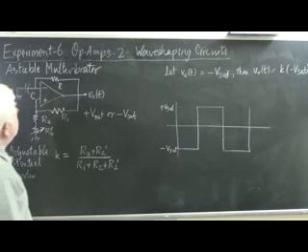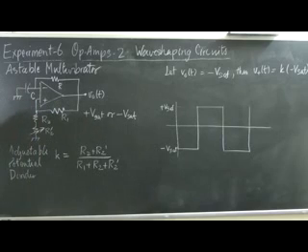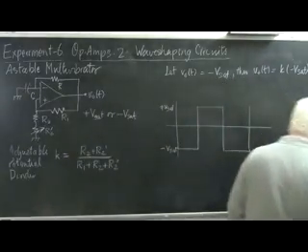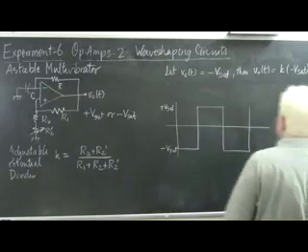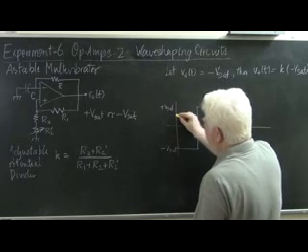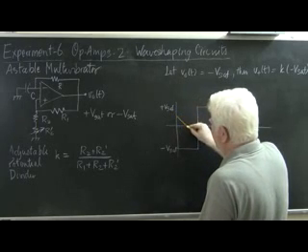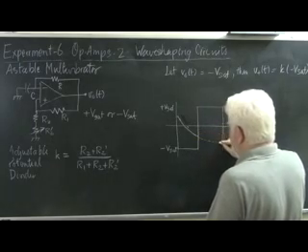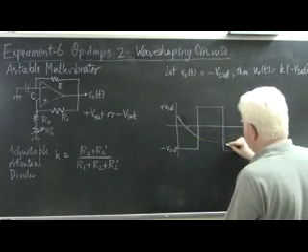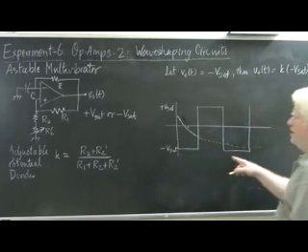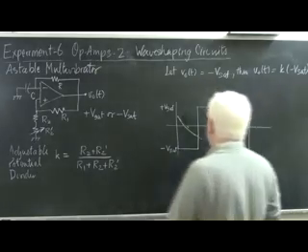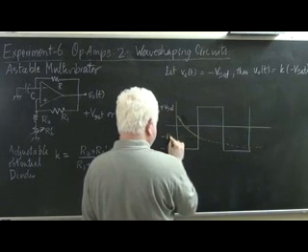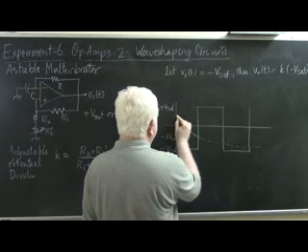So this capacitor starts charging towards minus Vsat, and this is how it goes. The capacitor starts charging towards minus Vsat like this, with an intention to eventually level off at minus Vsat. But what happens is that there is this threshold of k Vsat, or rather minus k Vsat,